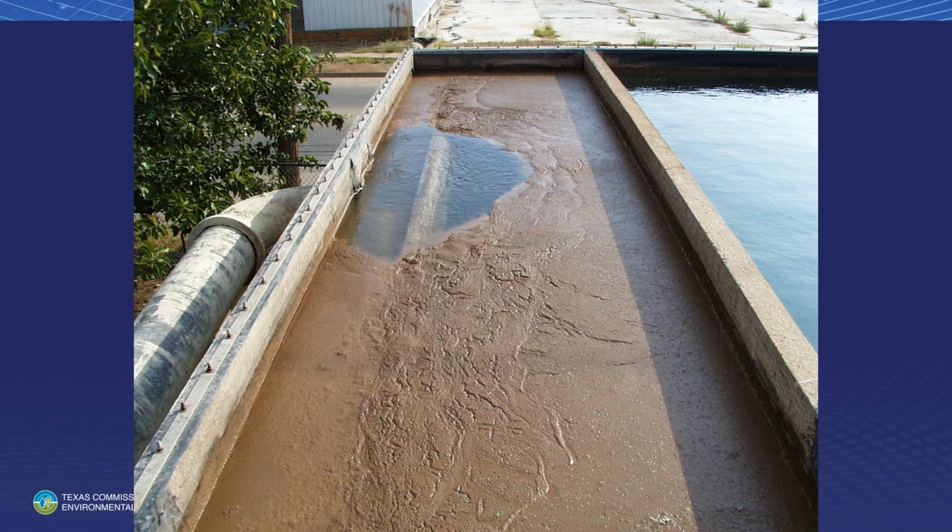Well, in West Texas, what they do is take lawn sprinklers and put them on the railings, and they hit that soap film with sprinkled water. It breaks up the soap bubbles, and everything goes right to the bottom of the clarifier. It's not an issue. But it is a little disconcerting when you walk up there as an investigator and see that kind of thing going on. It takes you a while to figure out exactly what's happening. So it's not a real serious problem, but it could be a problem.